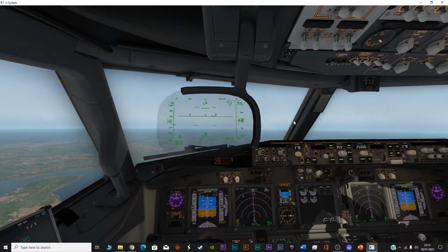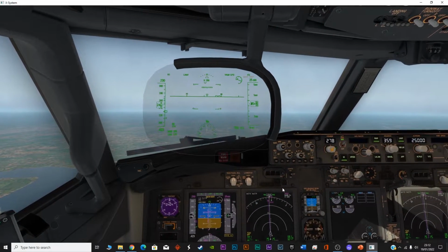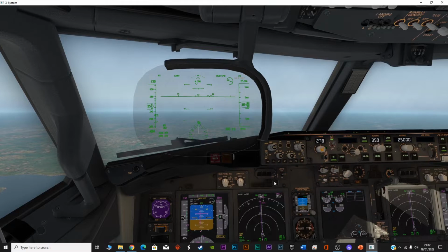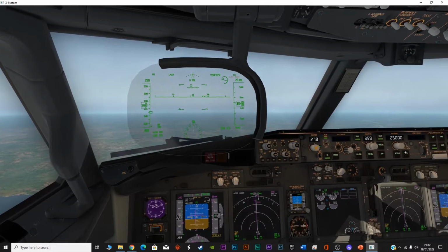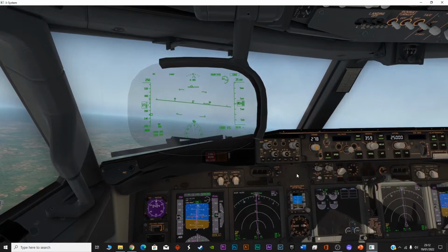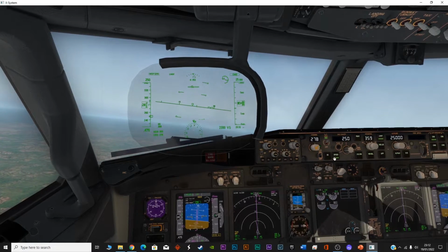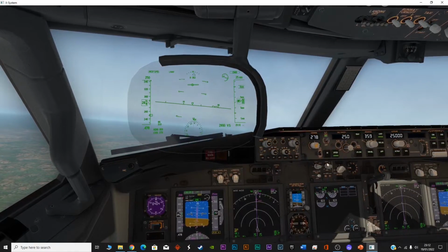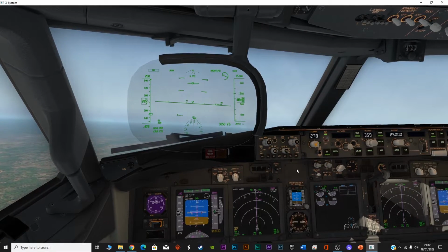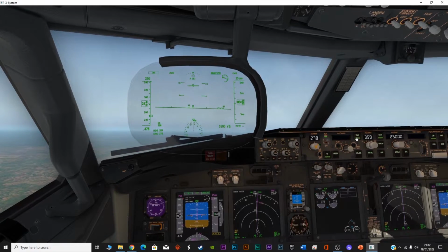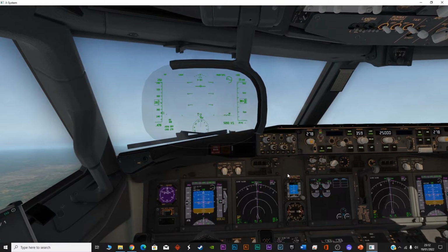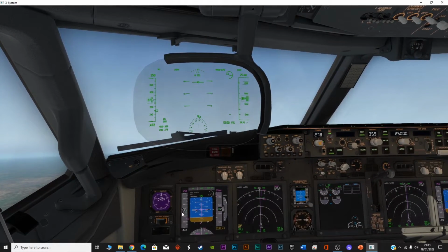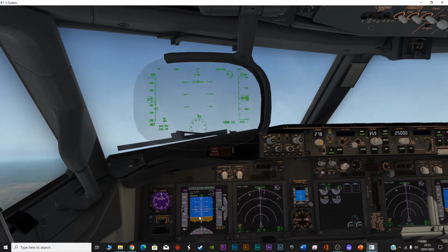Now the autopilot is engaged, and you will see the speed is increasing too much. Okay, this has also happened before as well. Let me just try this thing. This thing has happened before during the takeoff. So you can switch off the VNAV and try with the speed, and then this thing is happening. I think maybe some error or something like this. Look at the climb rate because it's trying to compensate for the speed. So that's why the climb rate is really high, 6,300.